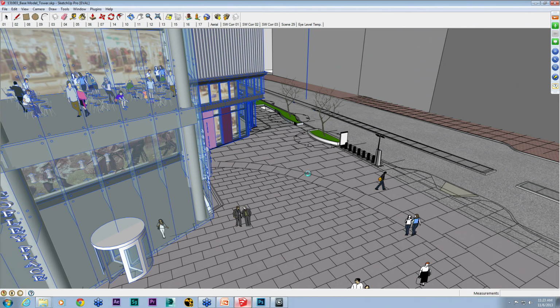So learning little things like that, or cleaning out little things like that, can speed up both your exporting from SketchUp and also importing into Max. I know before we started to establish standards like this and we were just doing direct imports, it could take a day to export from SketchUp and a day to import, which really slows down a production pipeline, especially if you're on a really tight schedule of 3 or 4 days to turn around a bunch of renderings. So we wanted to figure out a way to get it in and out as fast as possible.